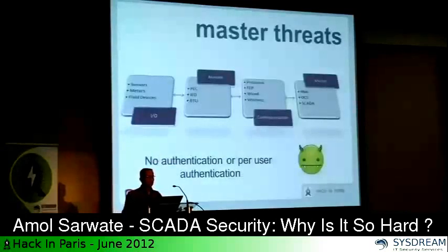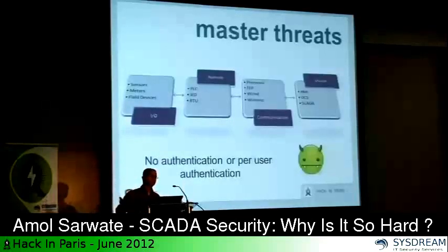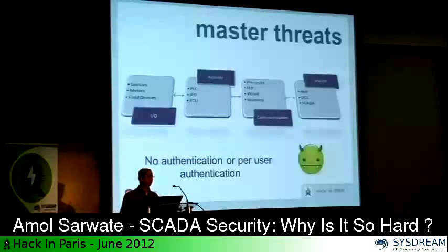No authentication, or per user authentication. When you go inside this facility which has command and control, there are a lot of machines with big displays that show what's happening in the SCADA network. But there itself, there is no authentication. If you are inside, you can just run there and type anything. Of course, there is no physical security threat, as physically you cannot get in there. But as I mentioned, if this network is connected to the corporate network or to the internet, viruses and malware can jump from your corporate network into these systems, and they can manipulate the HMI, or human machine interface, directly.